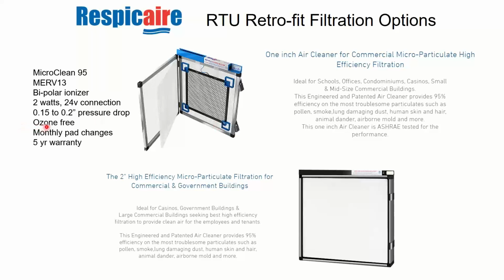And it's relatively low pressure drop, 0.15 to 0.2 inch pressure drop, which is pretty good. The power consumption is low, 2 watts on a 24-volt connection. That's basically 0, not really any energy penalty. And then you can get multiple configurations of sizes, and you can also use multiple sizes to slide them in together. But it's kind of nice. And then this grid charges stuff, which makes things bigger, and they're more easily caught on the filter. Same kind of concept, just like a little mini version of it. So keep that in mind for those kinds of applications.